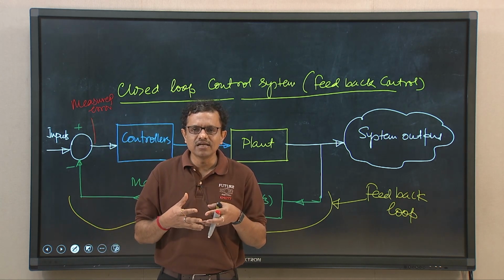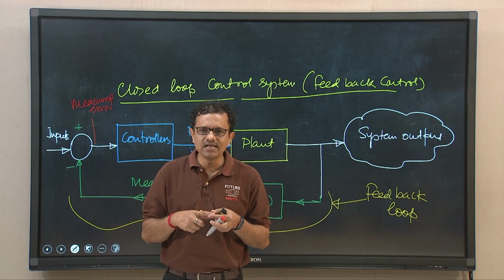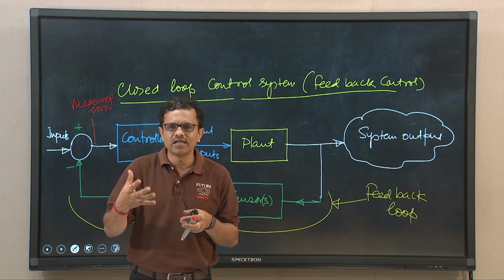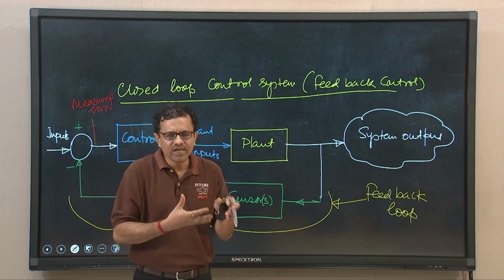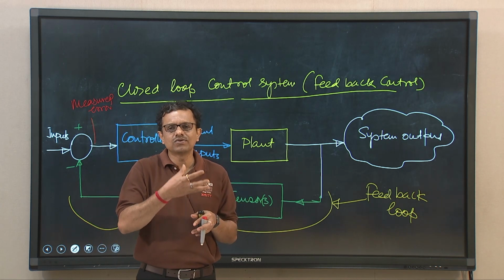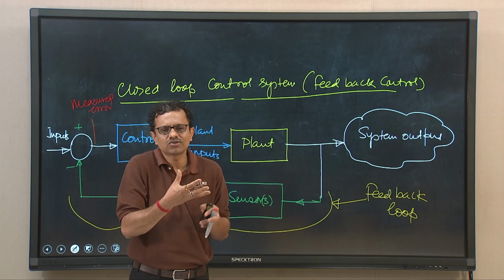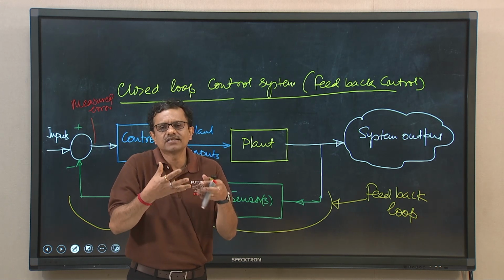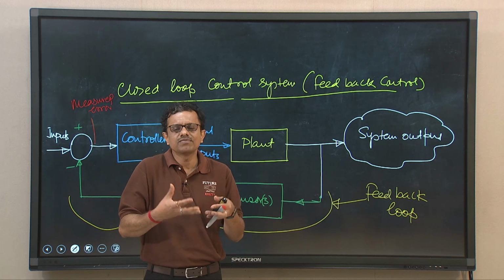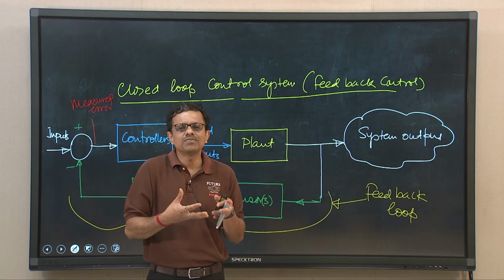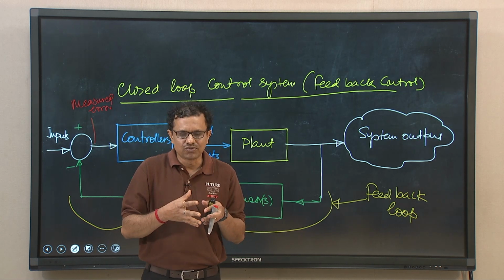What you can understand is that in the former case we had seen that even when the engine is going uphill, the speed will reduce and the engine will decelerate, but there is no way of giving that input to the plant, to the controllers, because the controller does not know what the plant is actually doing. So, because of the lack of this information, the engine will not be able to attain the desired output.